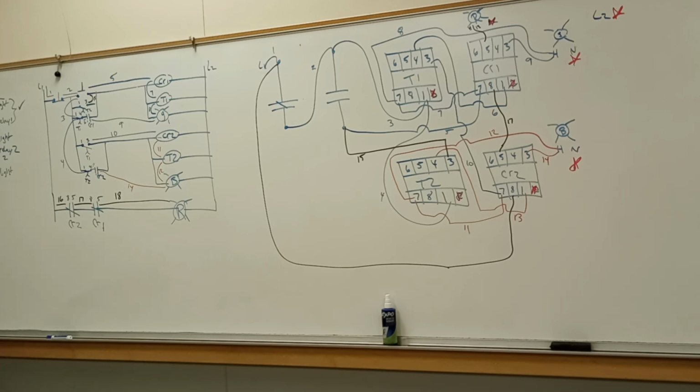When timer 1 normally open, is there any wire connected on number 1? At this one, of this part? See, that timer 1 is that timer 1. That's the exact same point. So see how I wrote the 1 and the 4? That's going to be the 1 and the 3. One's open, one's closed. So I need 16, the close set to disable the memory, and I need the open set to start the next process.